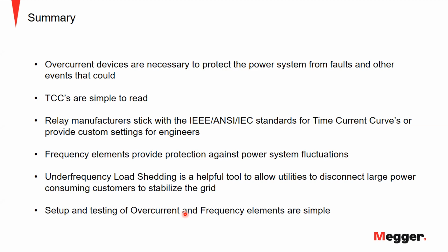And then the relay manufacturers always have the same standard. They go by specific standards, but also, like I was saying earlier, they provide custom settings. So you can create your own inverse time curve in case the ones that they have are not reasonable enough for you to use for your coordination.